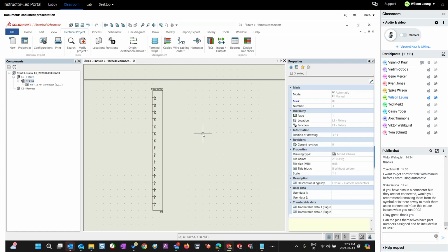So if you do not want this D-shaped connector or this rectangular connector, you can just show the pins if you only want to show the pins. And let's see how that would show up in your BOM. But in your bill of material, it's still going to show an actual component that you're buying, right? But the pins won't show in the BOM. So this was a method where I used an existing symbol from the library.